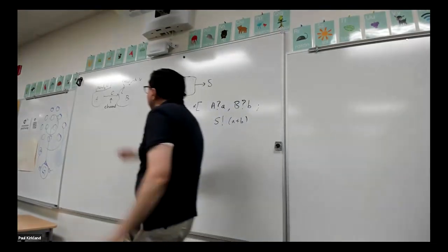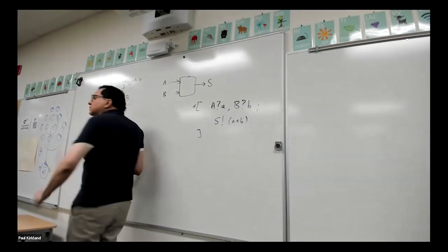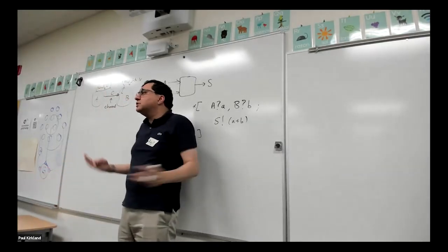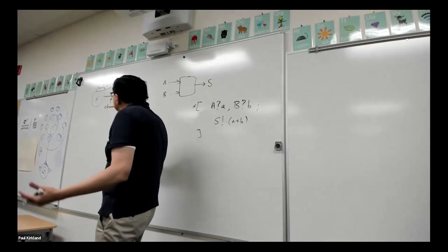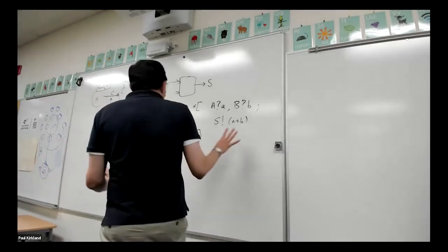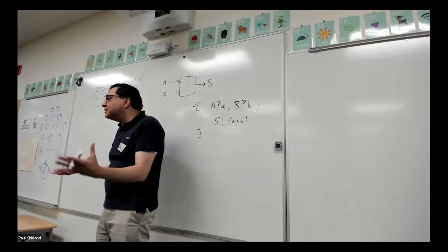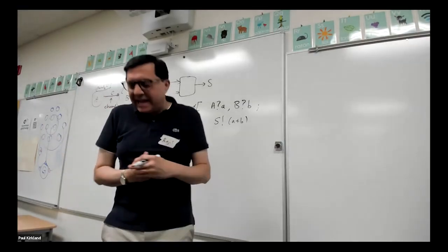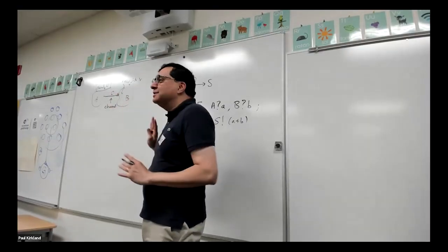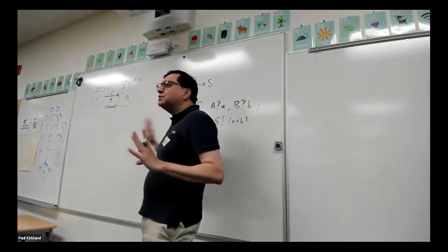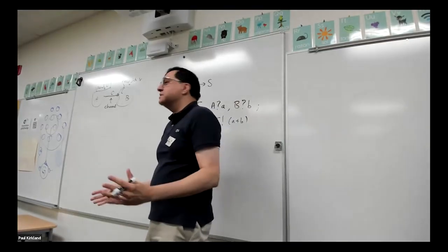So I've drawn this as a unidirectional arrow. This is a channel, but when I want to build a circuit I need to turn this into wires, gates and wires. This channel has some bit width. It turns out there are many, many different ways you can implement this channel. The CHP is the same, but the circuits will be quite different, and different implementations are good for different reasons.